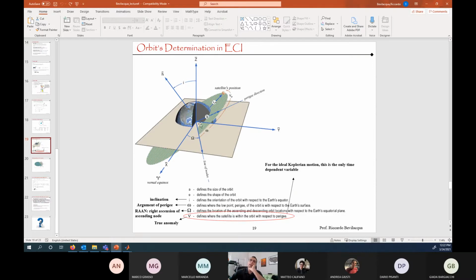So we still like to use the orbital parameters. It's just that we don't talk about them as constants anymore. We imagine that these orbits are morphing in time due to the perturbations, but we still imagine at any given time a frozen orbit that has a certain a, e, i, lowercase omega, capital omega, and it's just that they change instantaneously. Okay?